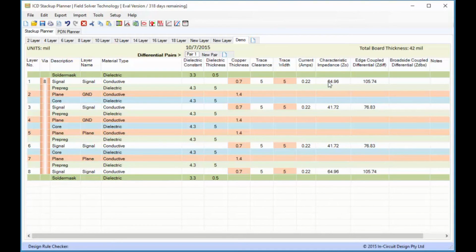How much time, maybe they waited a second too soon, or 10 seconds too early, you don't know. Plus you're dealing with chemical etching on the copper, so there's a bit of a potluck to it. They're always improving those manufacturing tolerances, but generally speaking, if you try to get this 50.0 on the money or 100.0 on the money, you're kind of wasting your time. So you want to get it in a near ballpark figure, and that's going to be good enough.